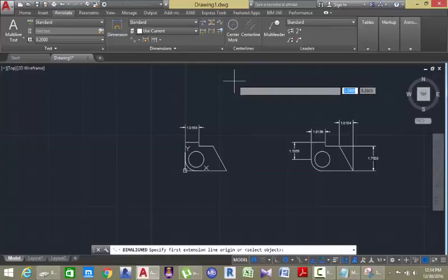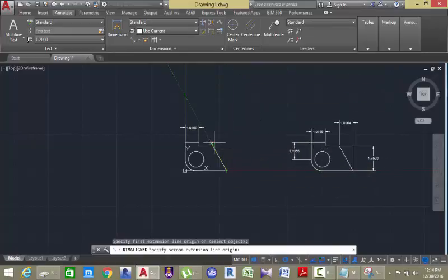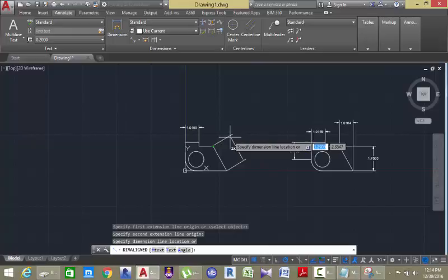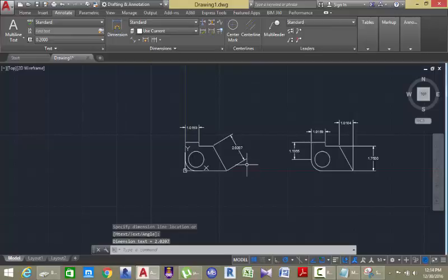So if I select this again, I click on this point, then again I click on this point. As you can see, this time, instead of the distance in the x and y axis, it follows the angle of the object and measures the line in true world. Now when I use the linear dimension, the 2 points give me 1.75, while the align dimension, the 2 points give me 2.0207. So this is the difference between the two.